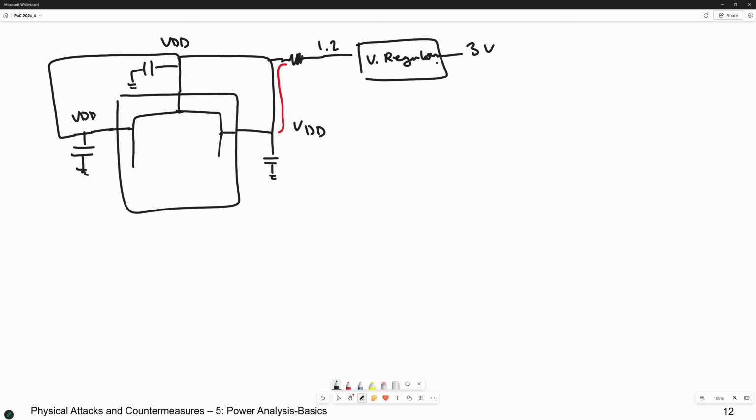That's okay, but these capacitors, what do they do? What is the purpose of them? To stabilize the signal. What you want to see is the voltage, so you can connect the oscilloscope to the VDD and the ground of the chip. These capacitors make the signal that you want to see completely smooth. They kill what you want to see, so you have to remove them.